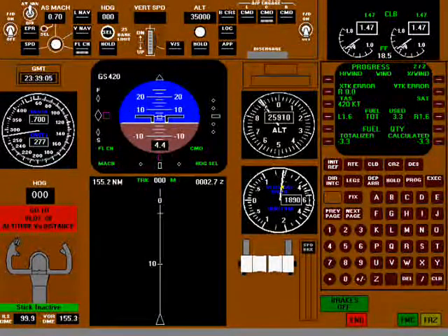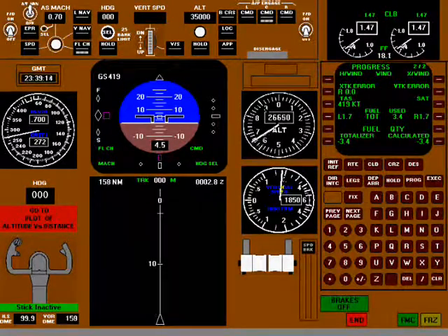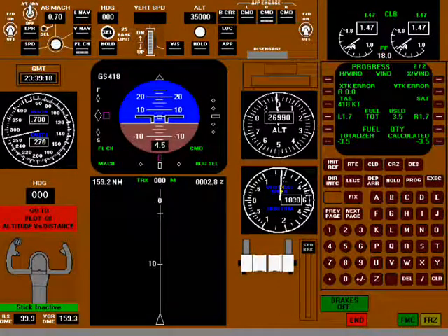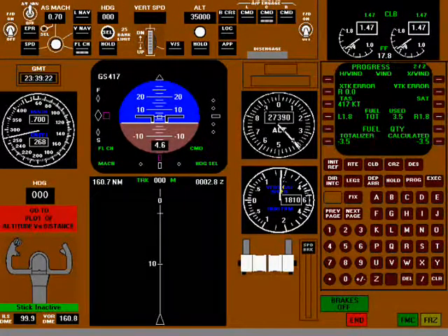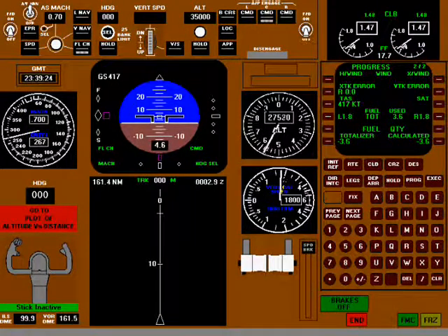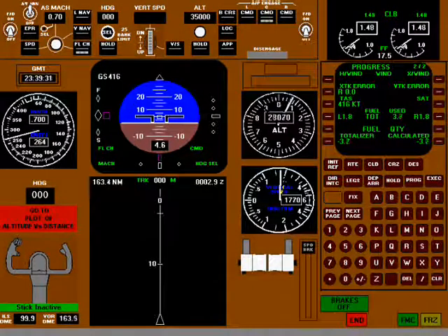The reason that rate of climb is greater during a constant Mach climb can be seen by examining energy relationships. The kinetic energy of the airplane depends on true airspeed. As true airspeed increases in the constant indicated airspeed climb, some of the engine power that produces the rate of climb is diverted into increasing the airplane's kinetic energy. During a constant Mach climb, true airspeed no longer increases, so more engine power is available to increase the rate of climb.